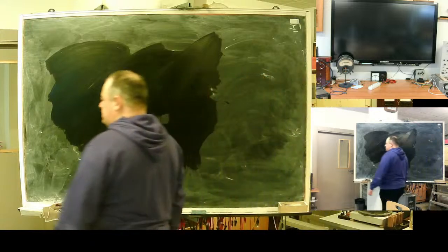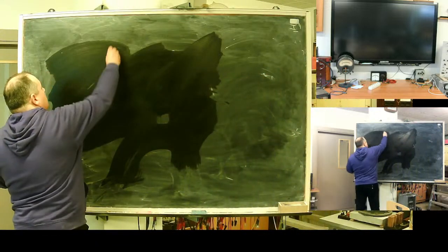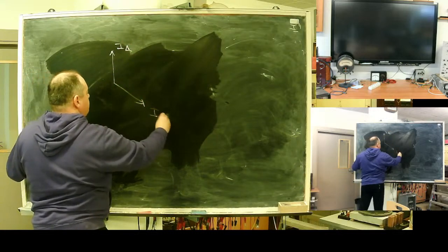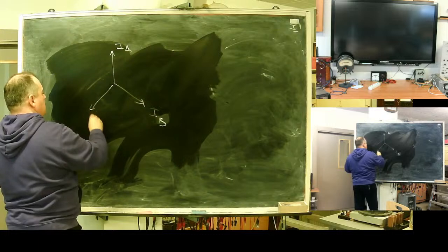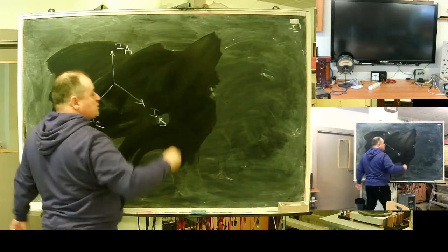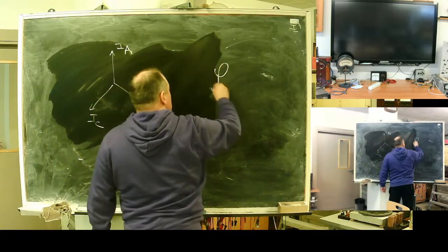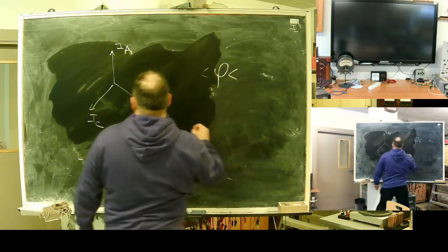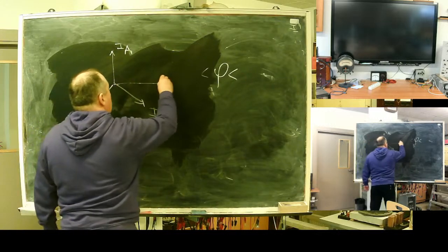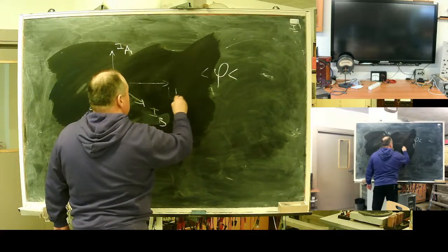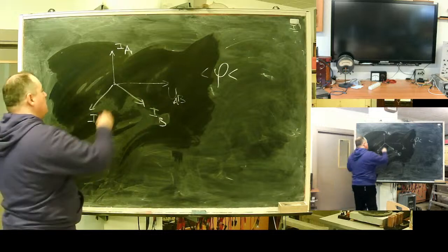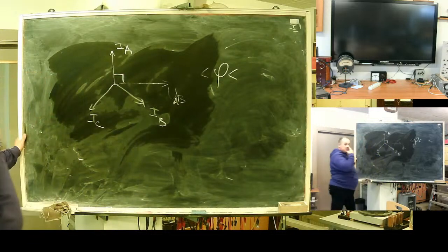What is the idea of the 90 degrees? I have A phase current, B phase current and C phase current. For my function, the angle between, as a polarizing value, AB voltage was chosen. That's why 90 degrees. It's the so-called 90 degrees schematics.